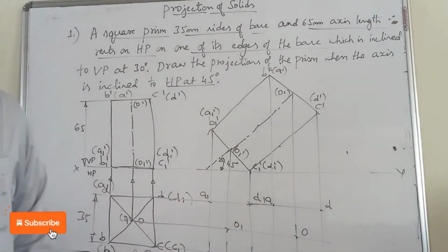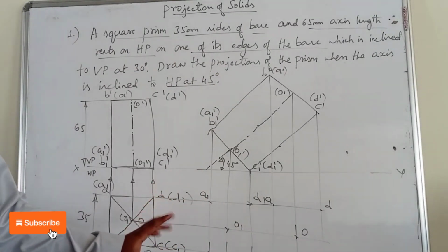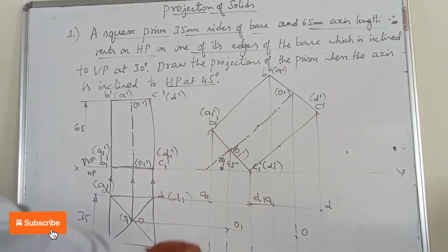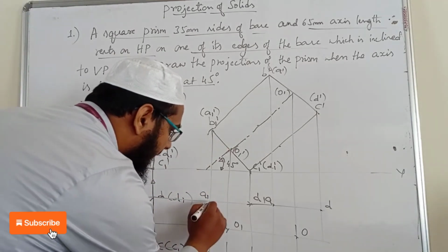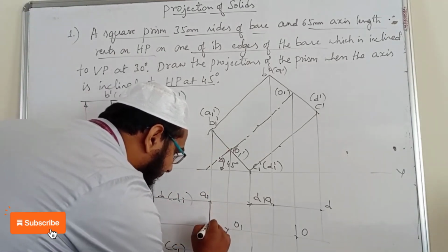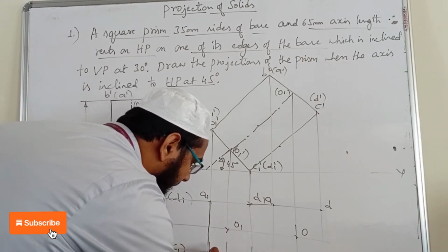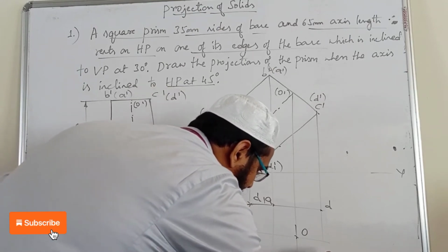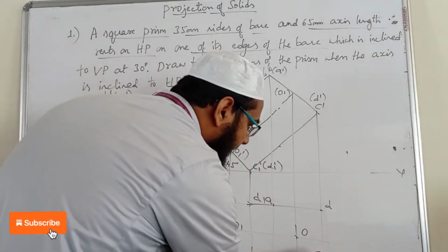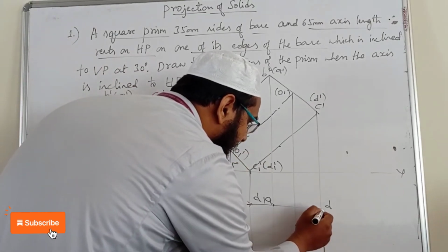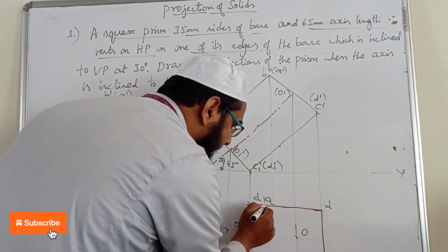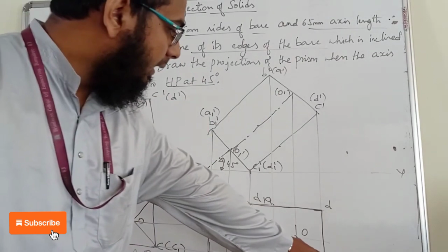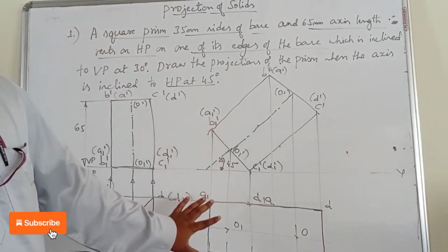Now you see the concept here. It involves 3 steps to construct the second position top view. First thing is you need to draw an outer boundary line. Remember it. You can see that I'm starting from the A1 point. A1 to B1, so that's an outer boundary line. Then B1 to C, another outer boundary line. Then from C to D, then D to A1. So this forms an outer boundary. That is the first step, the outer boundary line.